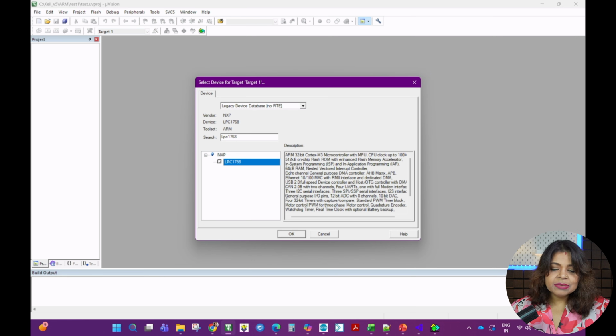Basically, in-system programming is programming without removing the MCU or the device from the socket of the board. You can program the flash through the serial port or the UART port of the microcontroller. In-application programming is where the application calls some APIs or functions given by NXP in their flash, some factory default programmed code that in turn will program the flash.